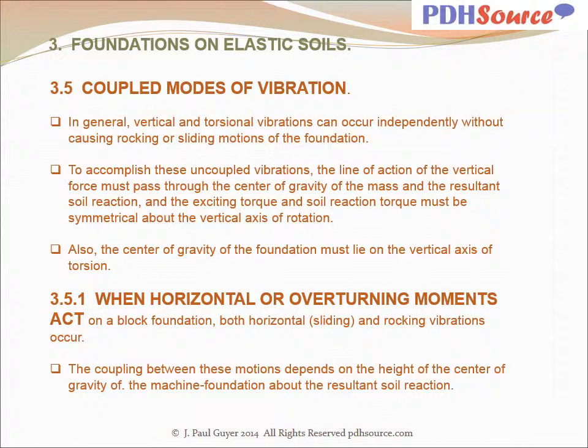When horizontal or overturning moments act on a block foundation, both horizontal sliding and rocking vibrations occur. The coupling between these motions depends on the height of the center of gravity of the machine foundation above the resultant soil reaction.